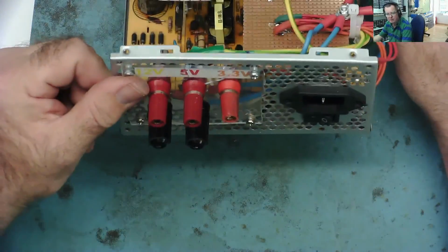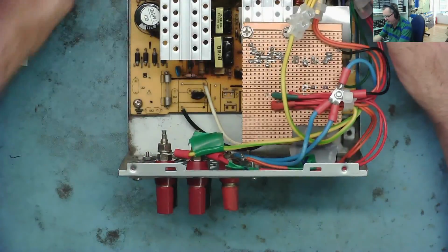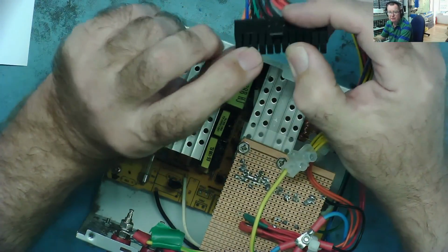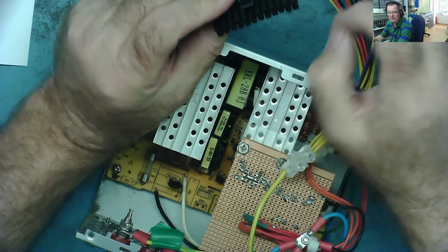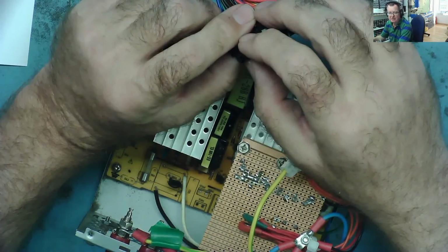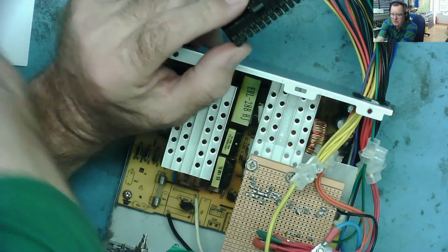So what we'll do now is connect the bench power supplies. We'll power the ATX up, and we can start it by grounding the green wire here. And I'm just going to check that all the voltages are present. If they are, then we can put our analyzer on and see what that thinks of it as well. Okay, so let's do that.